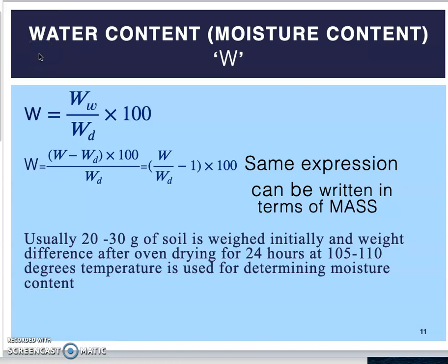Presence of water in any soil alters its properties, its cohesion, its friction. The moment these get affected, then naturally the strength of the soil will also get affected. The weight of the soil mass changes the moment there is water in the voids. Obviously, a soil mass without water will weigh much less.